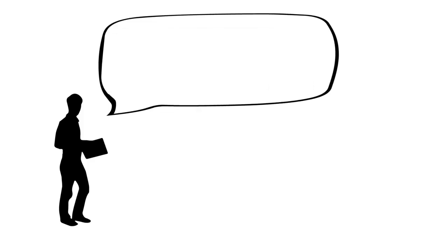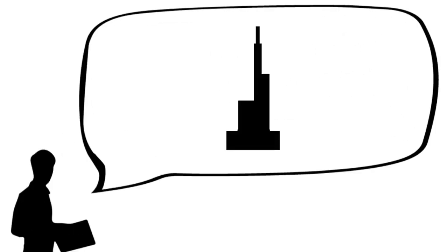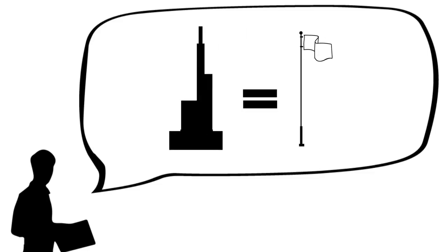Now, I just gave an in-person seminar at AIA New York, and one of the participants in that seminar asked, what about a really tall, slender building? Would that kind of behave at the scale of the building? If you were worried about buckling for the building, would that kind of behave in this way like a flagpole? And the answer is kind of yes. But in practice, the buckling would not be the biggest issue. In other words, you'd be much more concerned about other things.